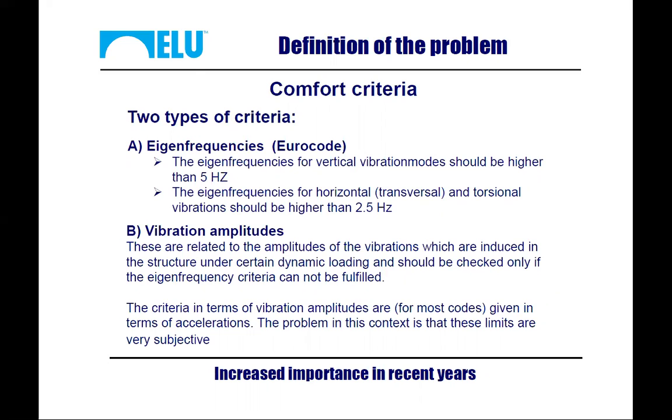What I can say about this criterion is that since I have started to look at this problem, I rarely, if any time, encountered a pedestrian bridge with frequencies higher than 5 Hertz. This is a very high value for the first fundamental vibration mode in the vertical direction, and it is rarely, very rarely fulfilled.